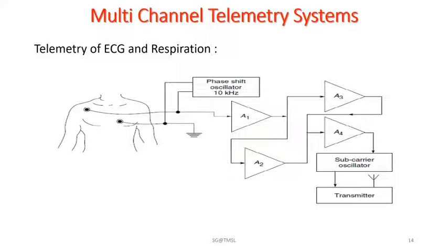In time division multiplexing, multiple signals are applied to a commutator circuit, and this circuit is basically an electronic switch that rapidly scans the signals from different channels, and an oscillator is used to drive this commutator circuit so that it samples each signal for an instant of time, thereby giving a pulse train sequence corresponding to the input signals.